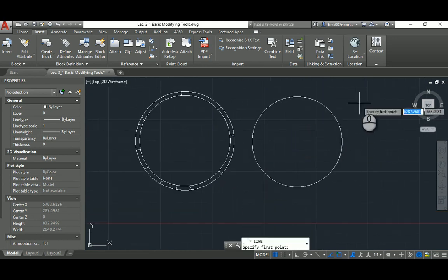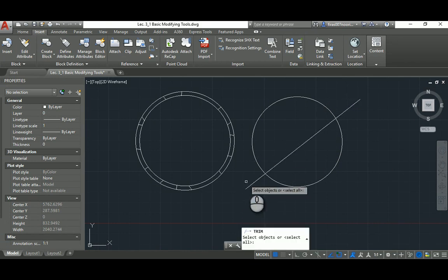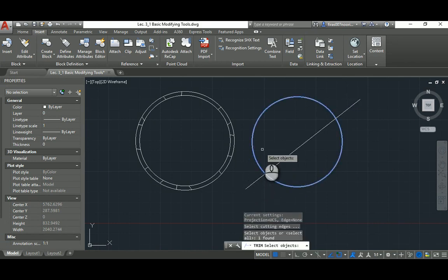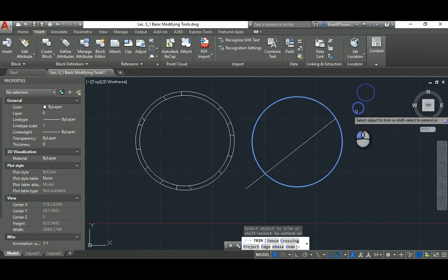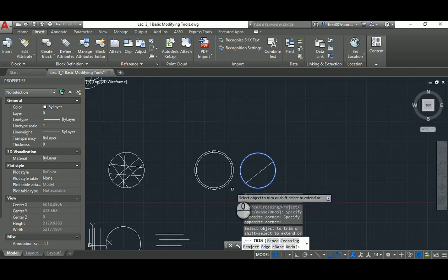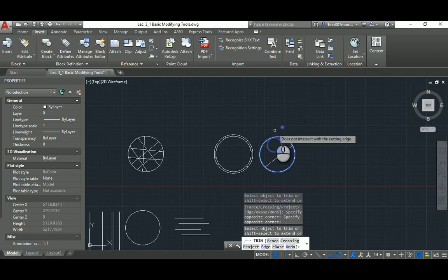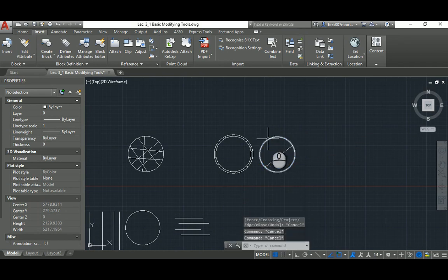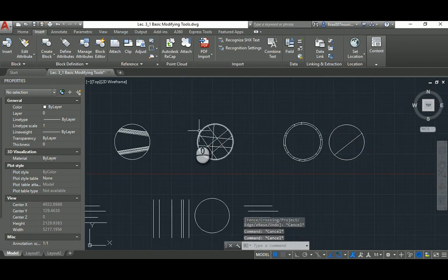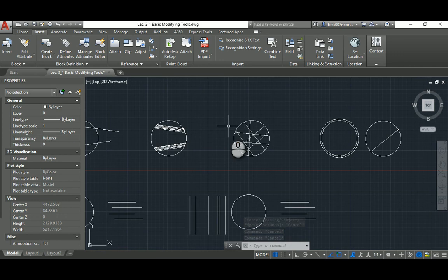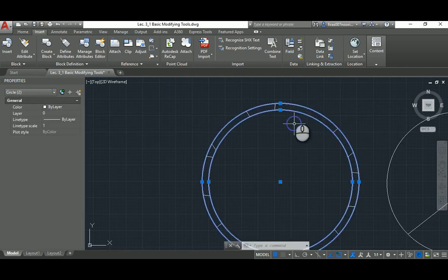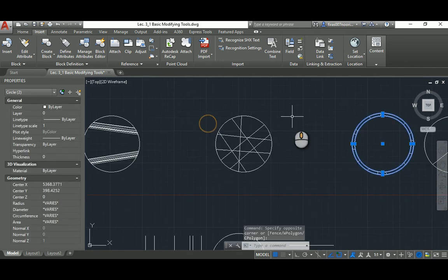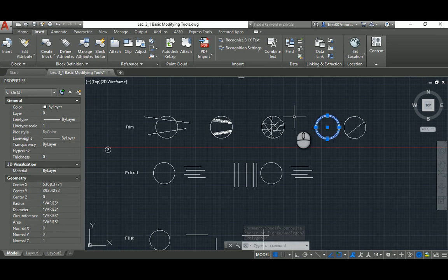Use that if you know that you need this circle to stay, and whatever other thing you select is going to be removed. So whenever you select the circle by mistake, it will not be cut. It could be really useful when you have too many objects in the same area, or located between two curvature objects, or with a complicated geometry, where you don't want to damage the walls, and you need something outside or inside, like hatch or dimension or tiles, to be removed